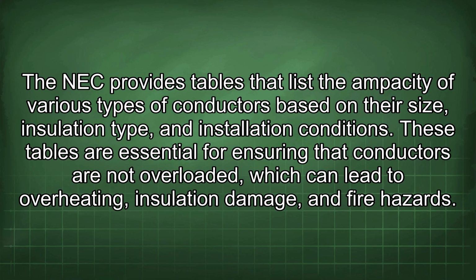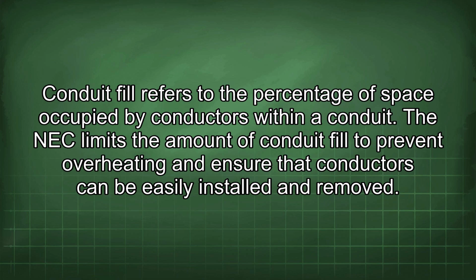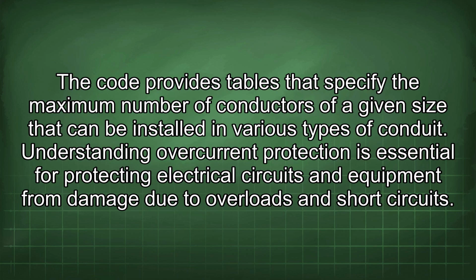and fire hazards. Conduit fill refers to the percentage of space occupied by conductors within a conduit. The NEC limits the amount of conduit fill to prevent overheating and ensure that conductors can be easily installed and removed. The code provides tables that specify the maximum number of conductors of a given size that can be installed in various types of conduit.